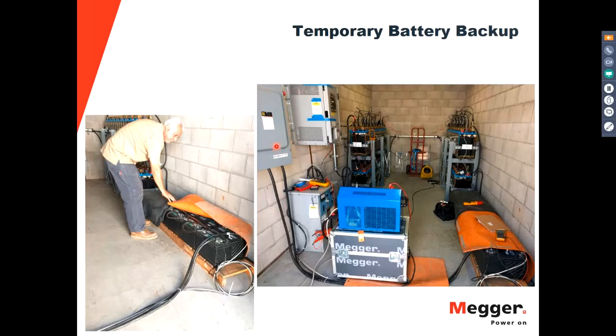The transfer switch is here, and from this box they can connect the new battery or put it in parallel with the existing battery, and then remove the battery to be tested from the system, and the substation doesn't see any problem there or any variation. So this is a very simple, quick, and very low cost solution.